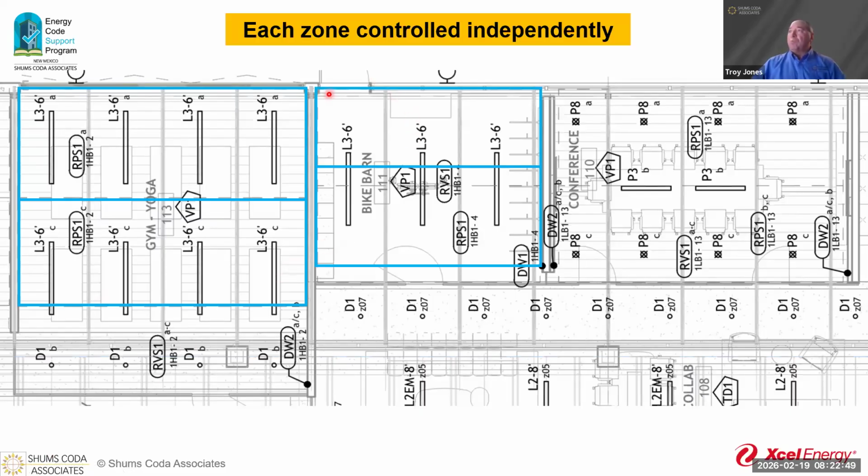So let's take a look here. We've got a storefront operation here. We've got a door. We've got windows coming across. This whole thing is our daylight zone. Now, we have walls here, so we're not going to be able to add to that. Obviously, if the whole room's got windows across it, we don't need to add that into the other side. I've had some folks try to do that before, making life a little more difficult. You got a full opaque wall there, no need to make that change. We have our primary zone, our secondary zone. We are on the way.